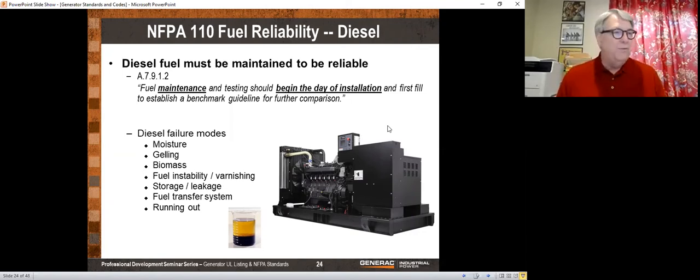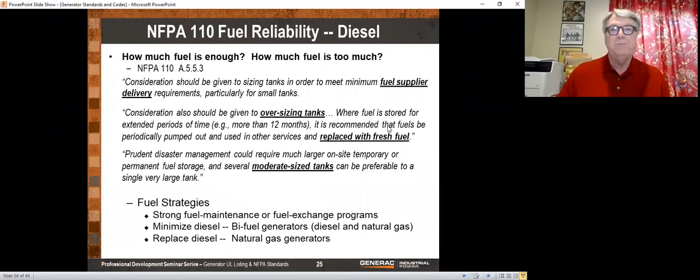So we replaced the fuel filter, all the problems went away, the generator was stable, it had nothing to do with harmonics. That's the number 2 reason for generator failure, fuel system failure of some sort, and that tends to be clogged fuel filters or dirty fuel that is either gelled or has water in it or so forth.